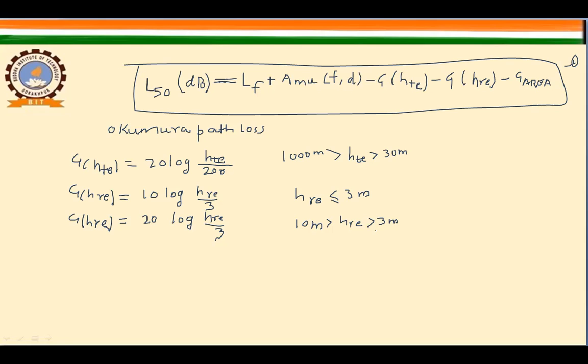So you can see this Okumura model is wholly based on measured data, and there is no provision for analytical explanations. So the Okumura model is considered to be among the simplest and best in terms of accuracy in path loss prediction, and it is very practical and has become a standard for system planning in modern land mobile radio systems in Japan.